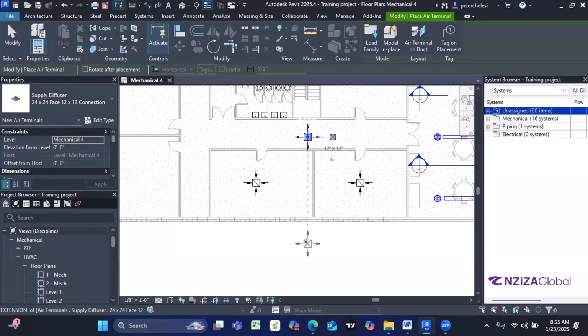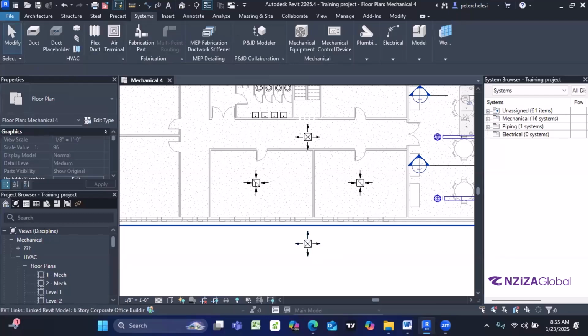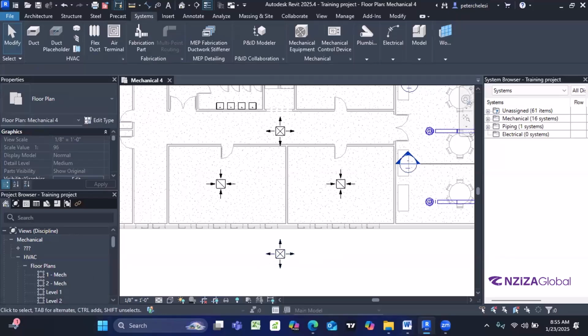So I want you to connect this system by using the duct. You can use the round duct. Then here at the intersection, I want you to make the offset in order to avoid the collision. So only 30 minutes, doing this exercise before we proceed further.